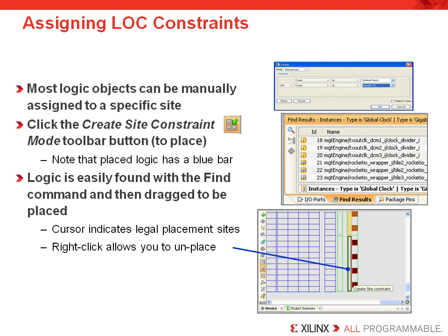Click the Create Site Constraints Mode toolbar button. Note that placed logic has a blue bar. Logic is easily found with a find command and then dragged to be placed. The cursor indicates legal placement sites, and right-click allows you to unplace.